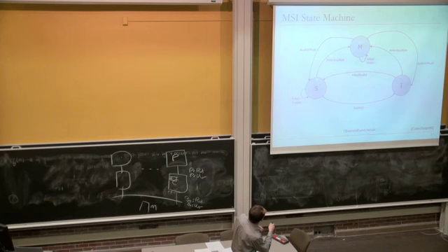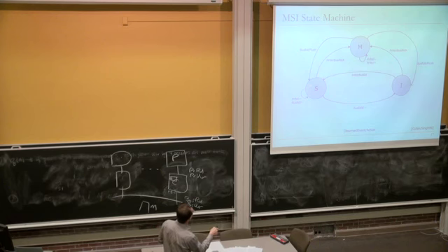Now let's see what happens if the processor wants to write to the block. It needs to transition from shared state to modified state. So it sends out a bus read exclusive signal, or bus write signal, let's call it. It's the same thing here. And when another processor that has the block in shared state receives a bus read exclusive signal, it goes to invalid state.